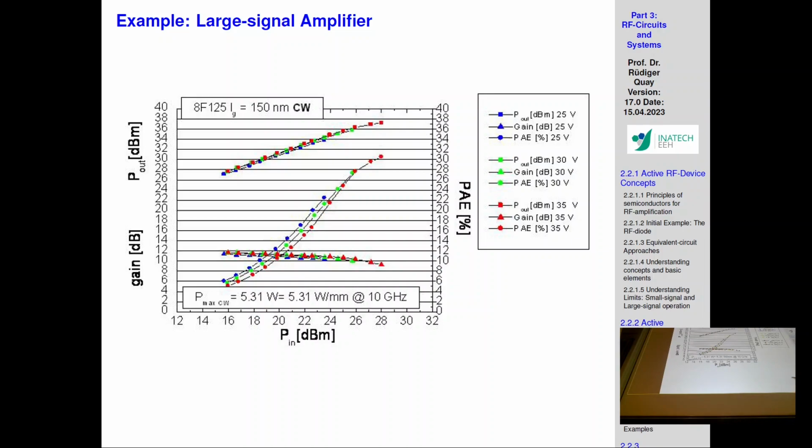And when moving to the right, when moving to a high input drive, high voltage, you can see that the linear part enters saturation of the output power. At some point, it starts to enter compression and then to break down. So that's the behavior. And we wanted to design there, the saturation part. We want to design there where we've exited the linearity aspect and we've entered into the aspect where our input power towards the output power diverges, then into 1 dB output point and then also a 3 dB output point.